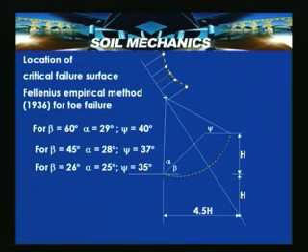Based on that, a number of failure surfaces can be generated. The program calculates the factor of safety of all these failure surfaces, and its efficiency depends upon correctly identifying the one which gives the lowest factor of safety. That happens to be the possible failure surface which can actually occur for the given section under analysis.